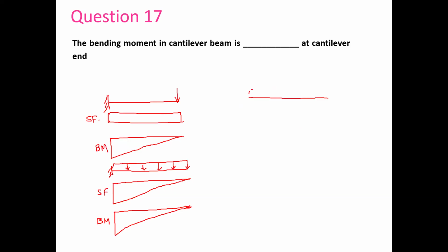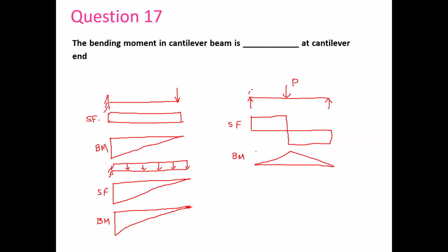If we go for simply supported with center concentrated load, then your diagram of shear force is in this fashion. So this is shear force. If we go for bending moment, then you have bending moment in this fashion. Linear line, linear. This is linear. Parabola. This is linear.